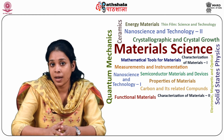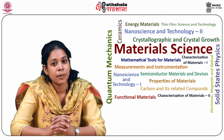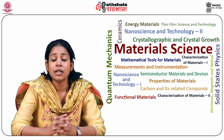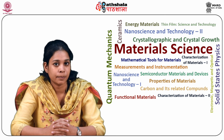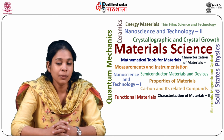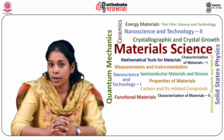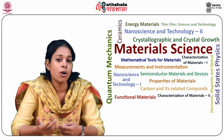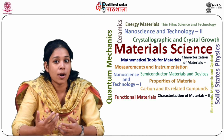The properties of alumina which we have read are high elastic moduli, high hardness, good tribological properties and wear resistance. It also has good mechanical strength with high temperature stability. But not all at the same time. The properties have to be optimized for a given application by controlling the purity and the microstructure. So the preparation also matters, how we are preparing the ceramics. It is prepared from bauxite ore.